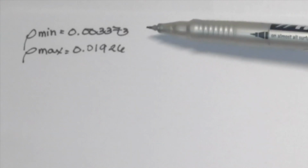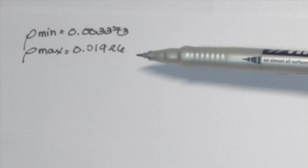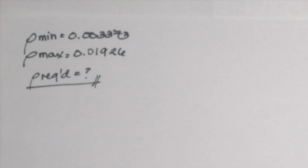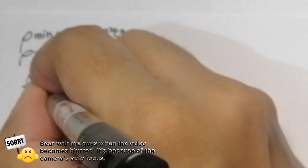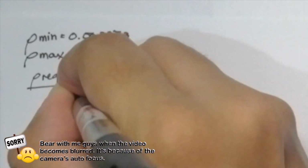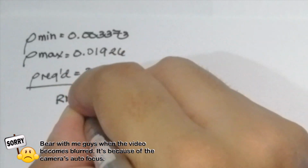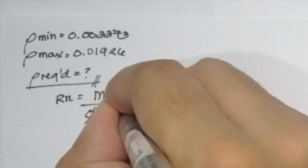Carrying over our values, the governing minimum reinforcement ratio is equal to 0.003373 and our maximum reinforcement ratio for tension-controlled singly reinforced beams is equal to 0.01926. So now we need to solve for our required reinforcement ratio before we can compare it to our limits. So our first step is to solve for Rn, or our coefficient of resisting moment.